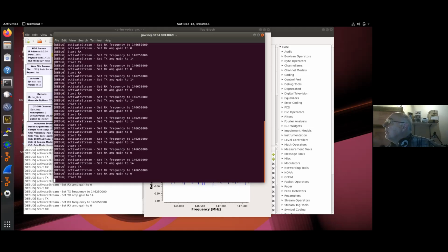Christoph asks, if I understand this correctly, you switch the HackRF to transmit by starving the transmit stream. And you're right, it is contrary to the recommended practice of GNU Radio. If you read the tutorials, they say, never starve your blocks. And if you write a block, not a tree module, it says you should always try to produce output and consume the input as fast as you can, and so on.